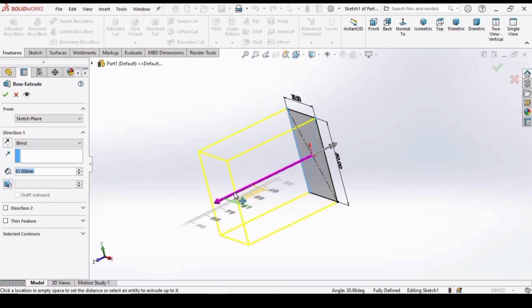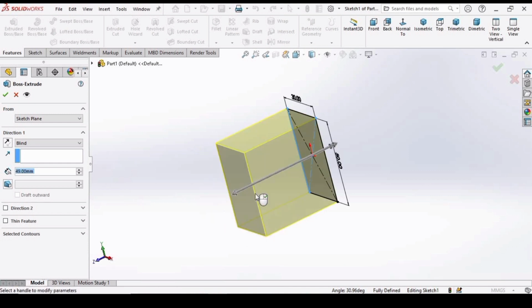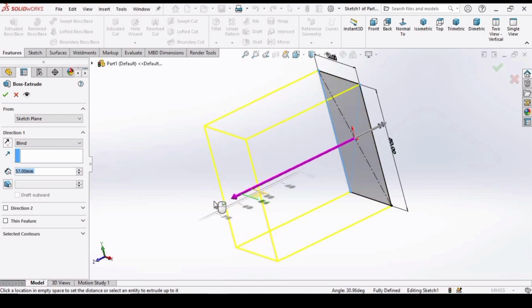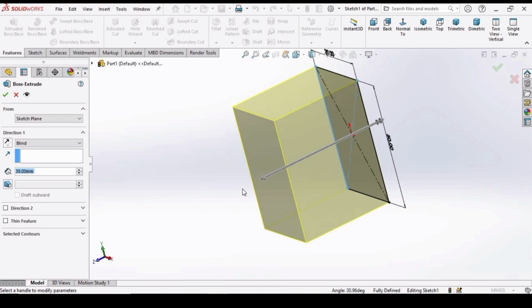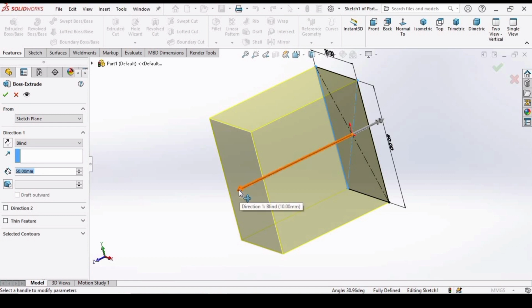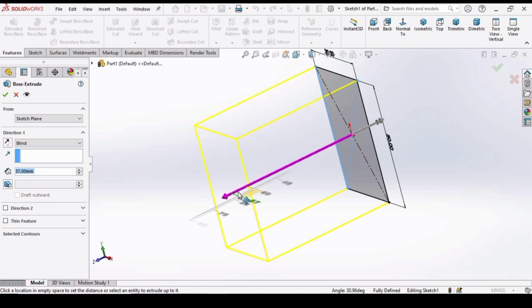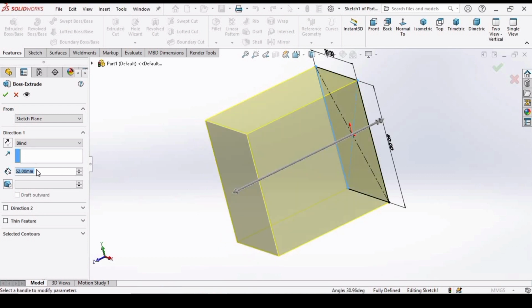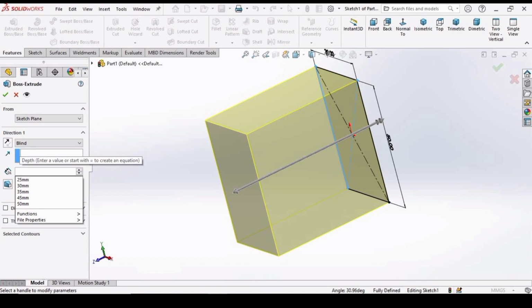But if you are working like a professional, or if you want to be a professional in SolidWorks, then do not just drag from here. Okay, because let's say this is 50. If we want to add 51.2, then you cannot just add like this. Okay, this is okay. But let me do the unprofessional way. I am pressing the backspace and adding 51.2, then pressing enter.